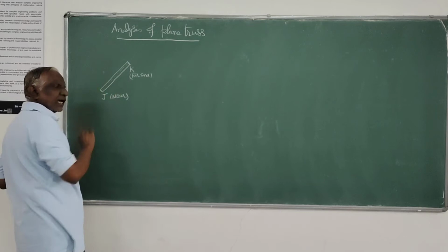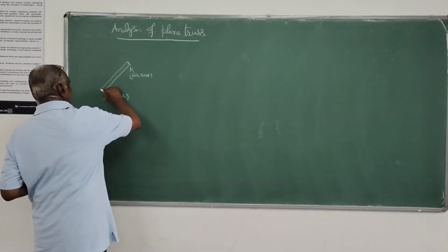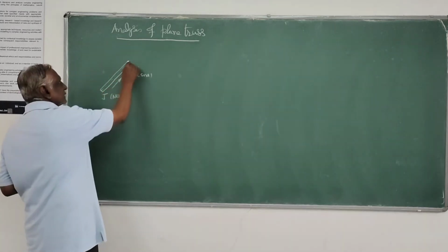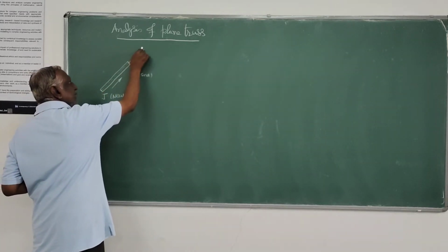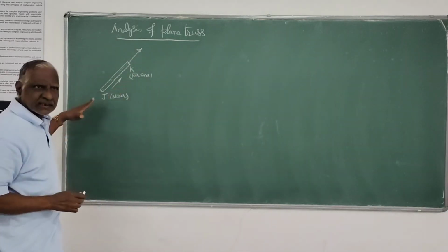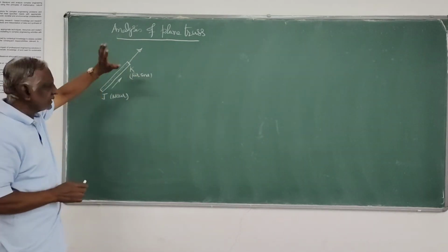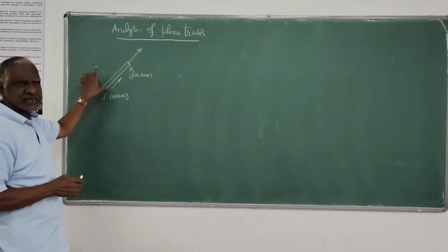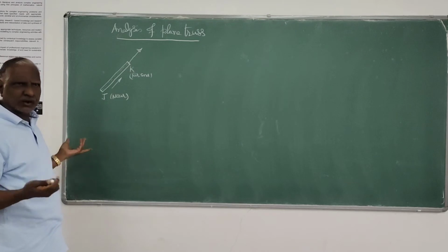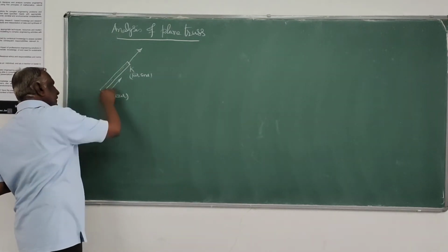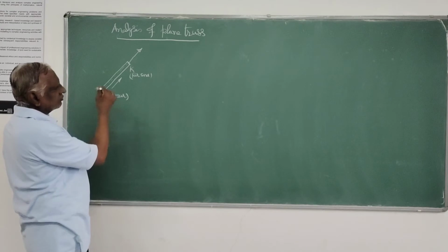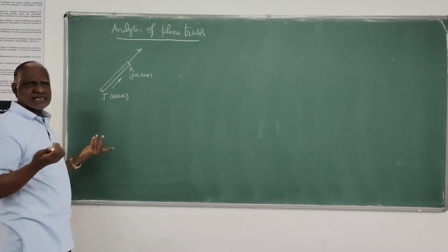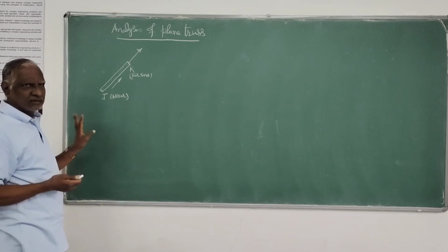Having assigned the near and far end of a particular member, the line from near end to far end, if you move in that direction, is called the member axis. That is one of the coordinate axes, called the member or local axis. The other two orthogonal axes we treat either in this direction as y or downward as y, and of course since it is a plane frame, normal to this plane is the z axis, which does not change.